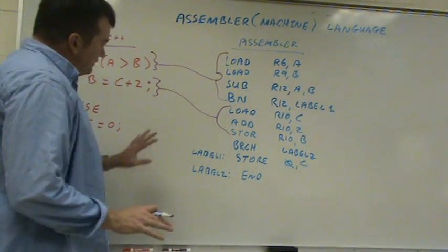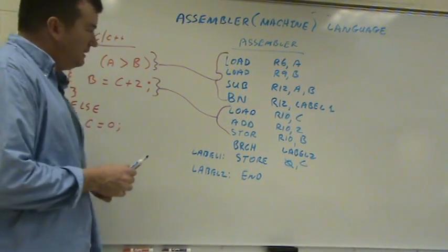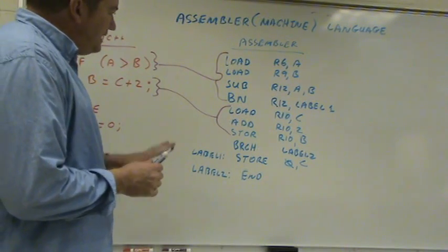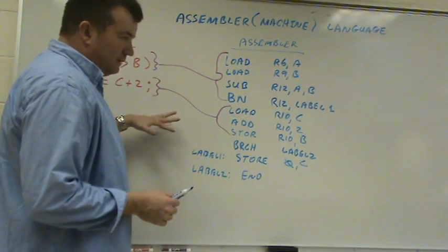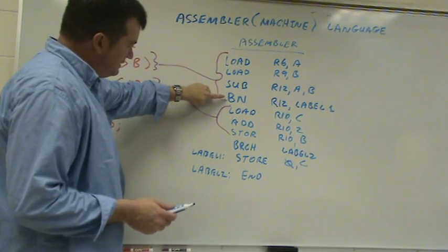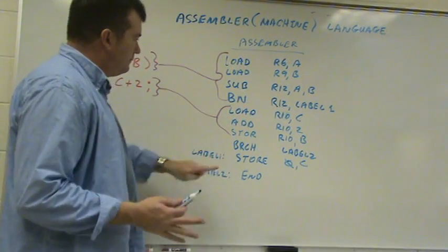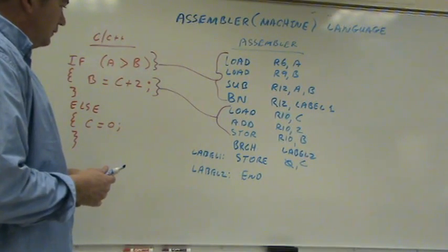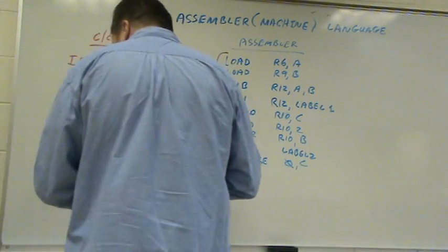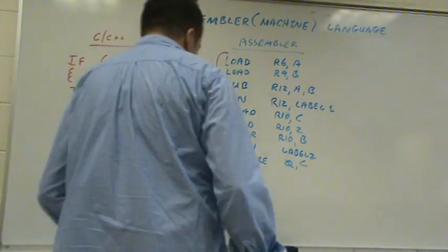So now the question is, this looks a little magic-y, this branching stuff. But could we come up with a piece of hardware that could branch based on a condition, just have a wire that's either true or false. If the wire is true, then the very next instruction is not the one right after it, it's go down to the label and start executing from here. Would that be a hard thing to do? So, let's first talk about how instructions are actually run.